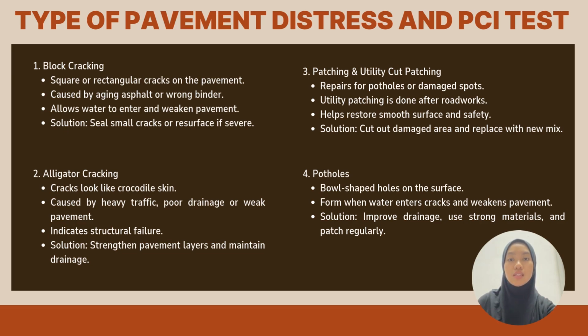So next is patching and utility cut patching. So we repair the damaged spots like potholes. Utility cuts are patches from roadwork. We cut the area and fill it with the new mix.